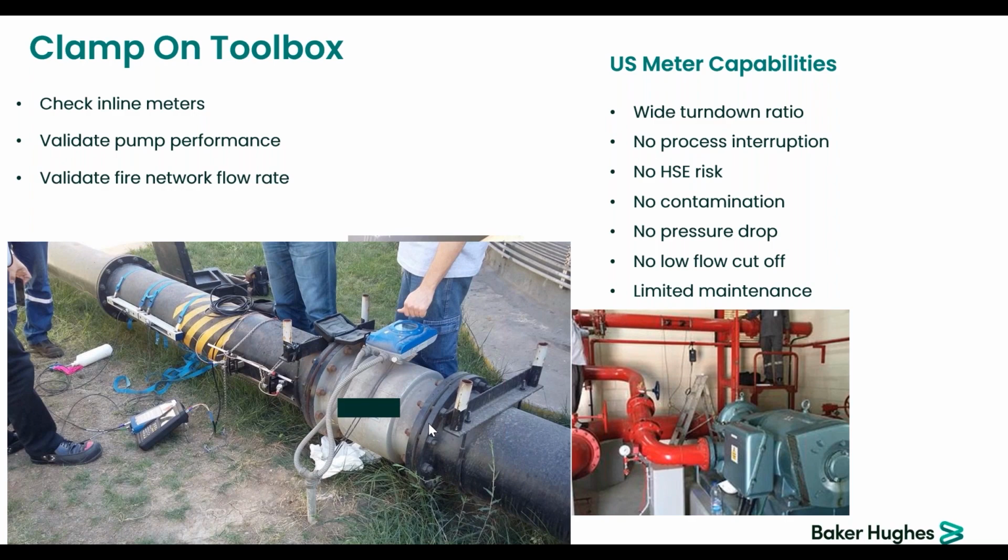So this one is sewage water, so a lot of solid content there. You can see there's a mag. Upstream of the mag, in this instance, we have our clamp-on, and there's another clamp-on upstream of our clamp-on. So there's no measurement here because this one was faulty. This one couldn't get a proper measurement because they had no signal, and we got very good signals.